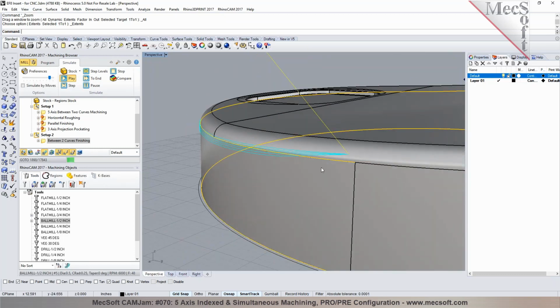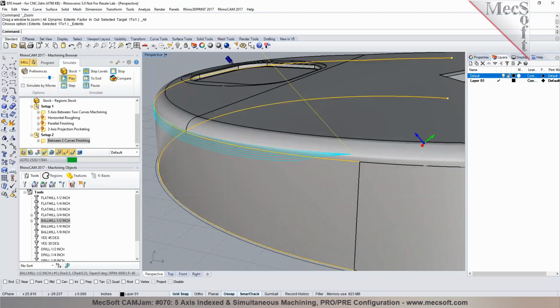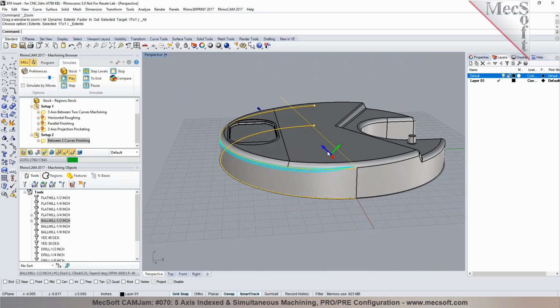What you have to do is break that up into smaller pieces. So in the case of index machining, you're locking the tool axis to be normal to that plane that you created out of this XY rotated plane, and you're just programming a 3-axis operation. So you may have to break it up into maybe 2 or more sections, right? So that's called index machining, and we will still output the angles for it.